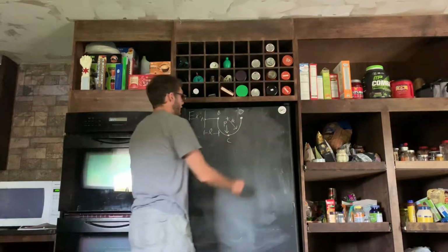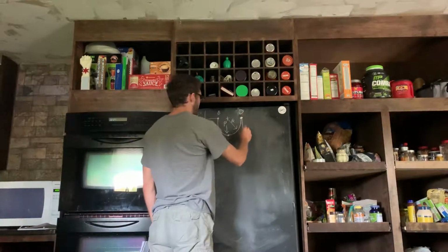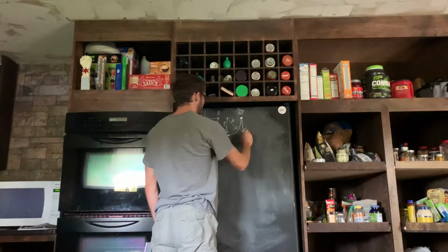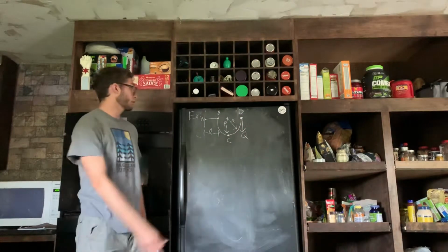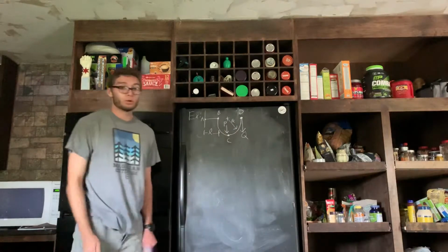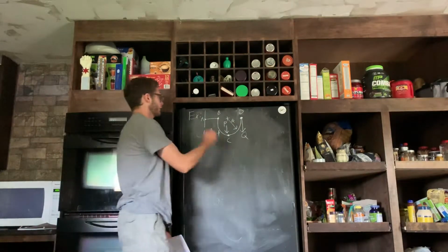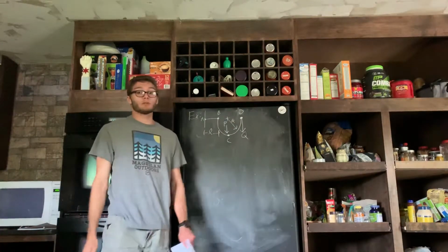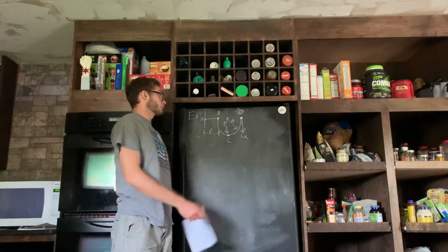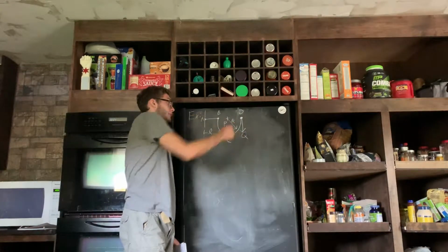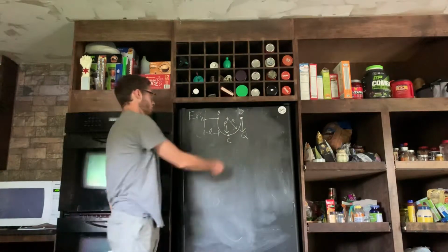Instead, we have to apply a fictitious force Q at the point where we are trying to solve for the deflection. In this particular problem, I just want to solve for vertical deflection, so my Q is going straight down, similar to P.